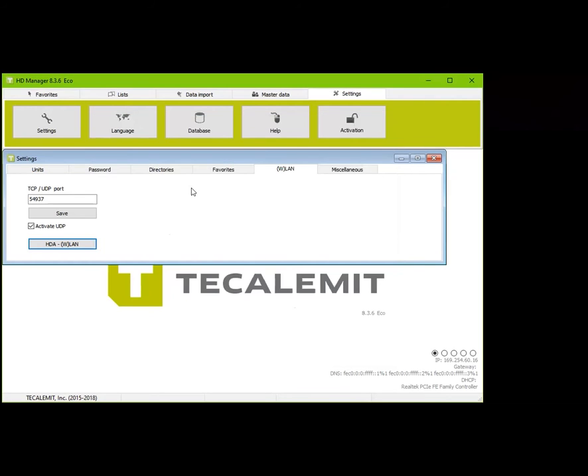So once we save that config file on our stick, we're going to take it out either to our Wonderbox. If you're going out to your Wonderbox, your box should already say when you power it up, invalid config. You're going to hit enter there, and you're going to insert the stick, and it's going to go out and look for that LAN connection or that Wi-Fi connection, and then your box is automatically going to populate to the software. Now, the software and the box do have to be on the same network. So we want to make sure that we have that so that our software can see our box.